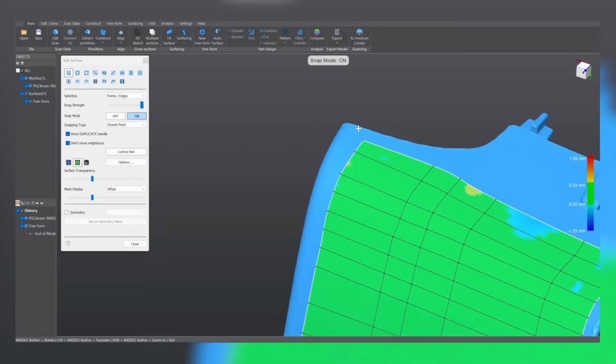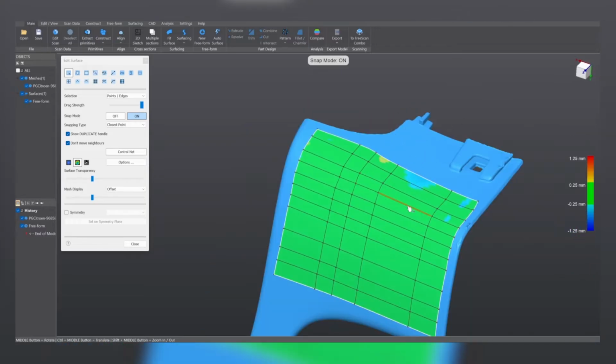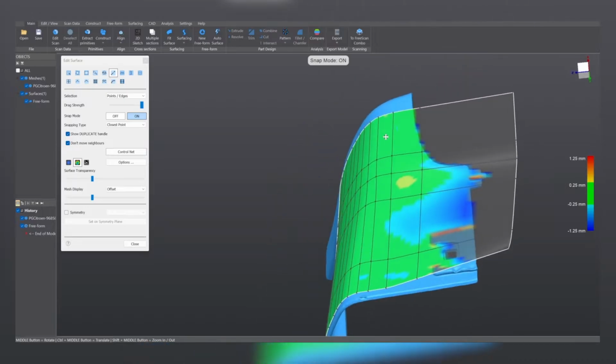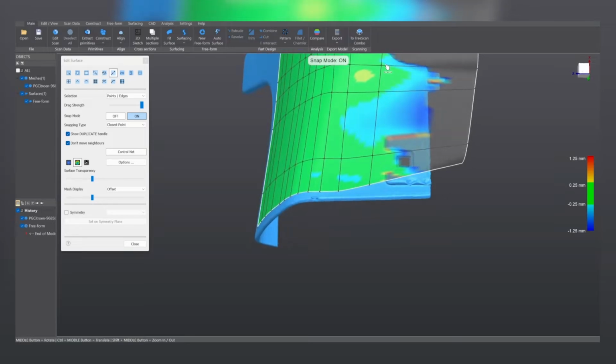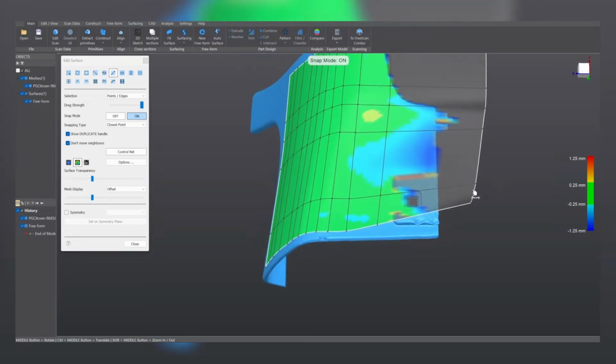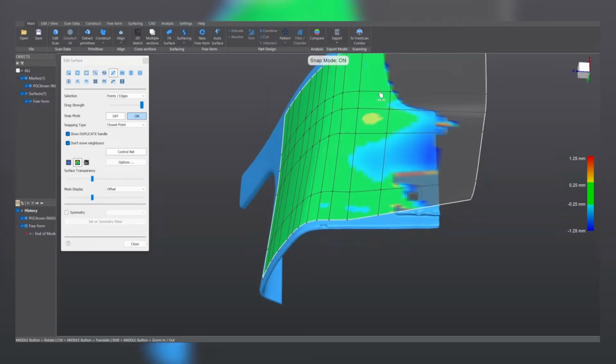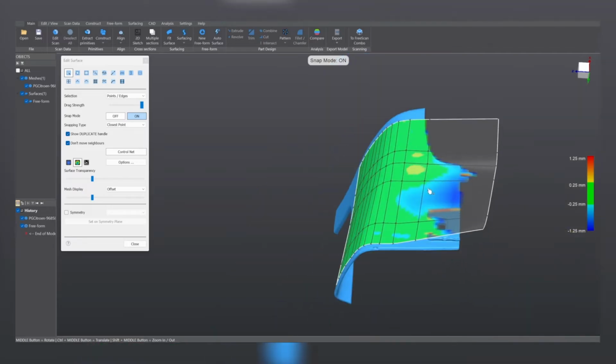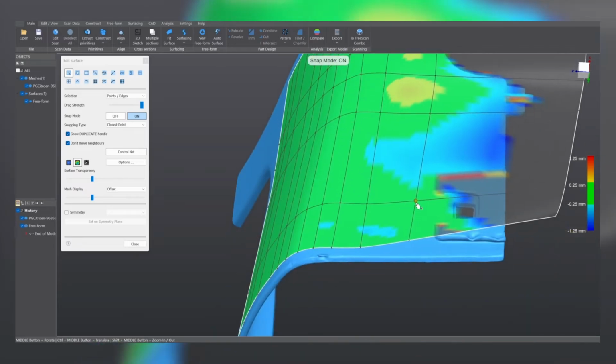And now, instead of extruding more and more faces, we are going to extrapolate the current surface that we have. So we click on here and we select the edge and we extrapolate it. Okay, now we have points, vertices of this surface that are onto the mesh and points that are not onto the mesh, right? So let's first take care of the points that are onto the mesh. We go to manipulate, and with the snap mode on, we move them a little bit and let them snap onto the mesh to give us a surface that adjusts well to the mesh.